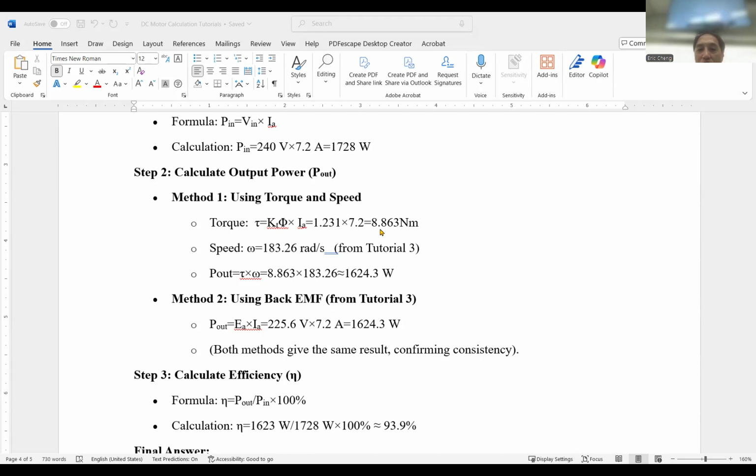When we have low voltage, then we have lower back EMF voltage, because we are now doing motoring, and the motor back EMF voltage must be less than the input voltage. So now that's how we get to this calculation. Very simple, straightforward. Same as previously, but we are just adding a chopper to reduce the voltage. That's all. We don't have any complication here.